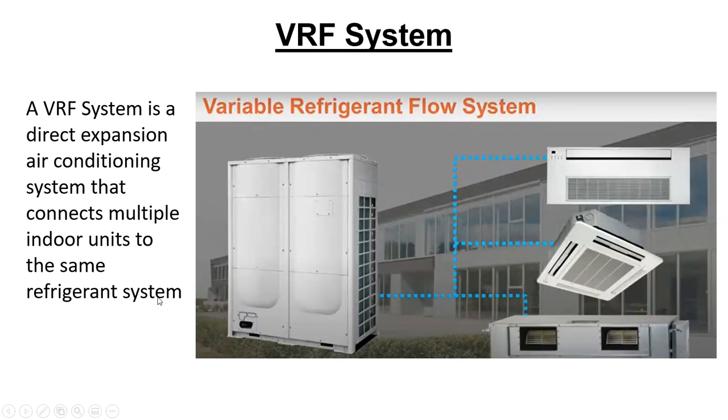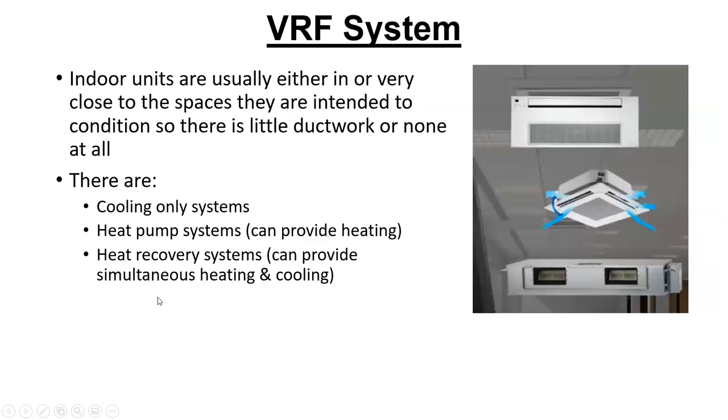We don't have chilled water that we're cooling down and circulating. We're actually circulating the refrigerant, be it hot refrigerant or cold refrigerant, to the different indoor units to make this thing work, okay? And so we'll see that we can have one outside unit and multiple. Well, we'll see as we go through the slides here.